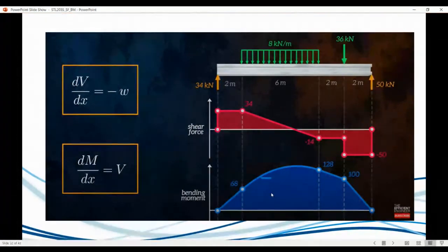So if you look at your bending moment diagram, and what's kind of funny, when your shear force is typically 0, your bending moment is normally at the maximum, and we'll discuss that shortly. And at that particular point, you must be careful where you'll be applying anything, because that's where the beam is most likely to fail. Your bending moment is at the max there. So that's the kind of way you want to view it.